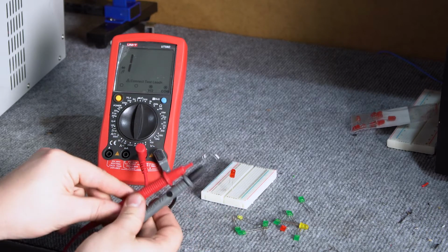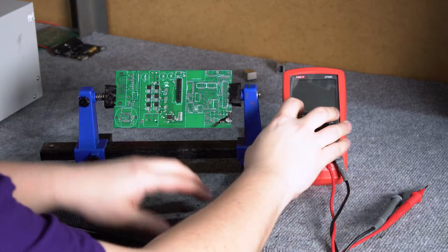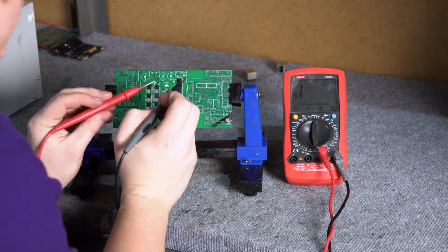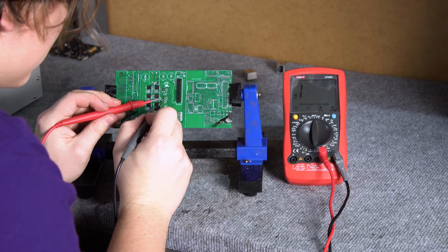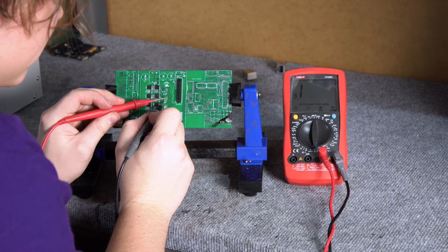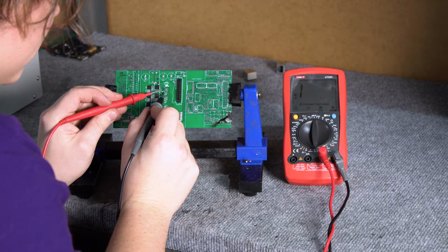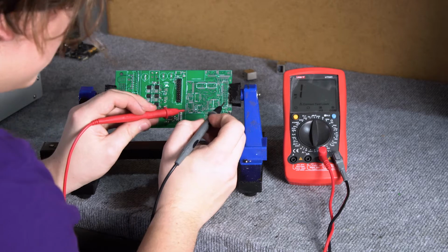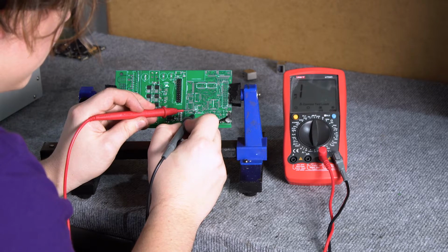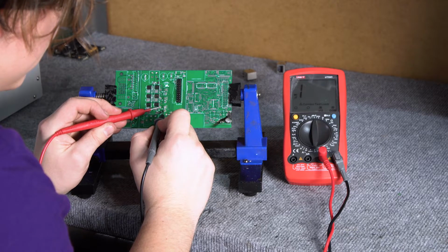Reading may be distorted. The circuit continuity tester is usually located in the same place as the diode tester. Its operation is based on the fact that if the meter detects a resistance below usually 75 ohms, it will start to squeak through the piezoelectric transducer. It is useful for checking short circuits or connections on complicated PCBs. Sometimes we may not be aware that a very thin path has been interrupted and we cannot observe it with the naked eye. It is enough to apply one probe to the place on the element and the other on the place where the path is to go. We will find out through the sound whether there is a connection or not.